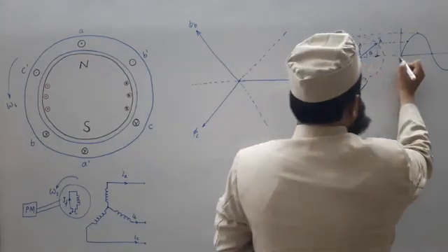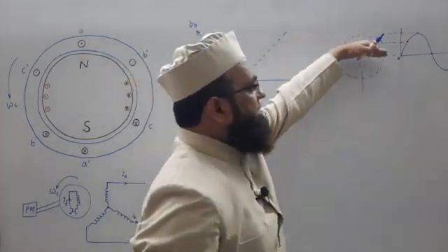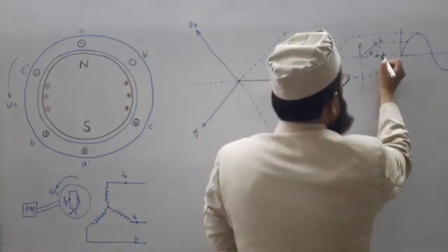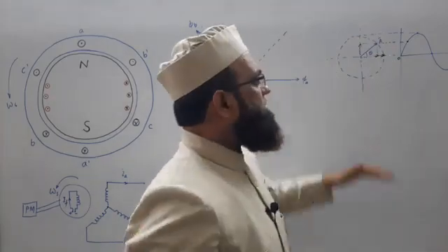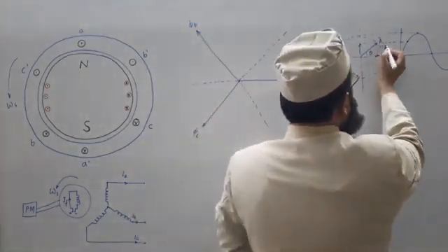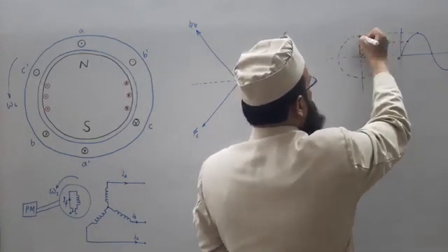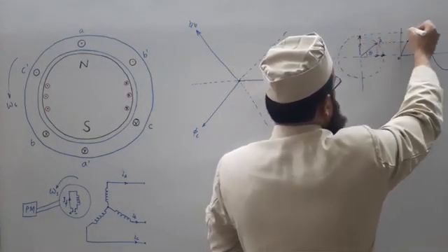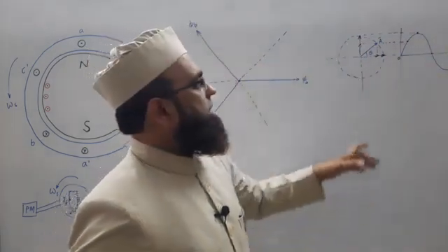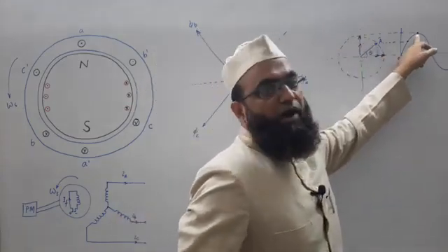At this point, let us say this is 0, this is our reference starting from here. Starting from here, this phasor is lying along the horizontal position, right. So what will be the vertical projection? 0. After this, at this moment, the vertical projection is this. When it has reached this position, what will be the vertical projection? This. So the instantaneous value in quarter 1 increases from 0 to some maximum value.